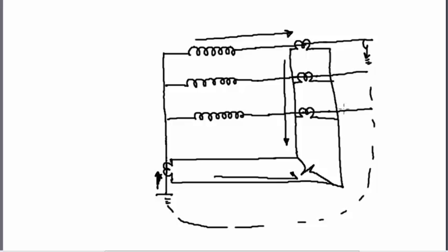getting any current. Now suppose that this fault current was so high that this CT got saturated, means saturation occurred in this CT. So now it is assumed that when the CT got saturated, this current became zero. Now I is equal to 0, hence this current has no value.